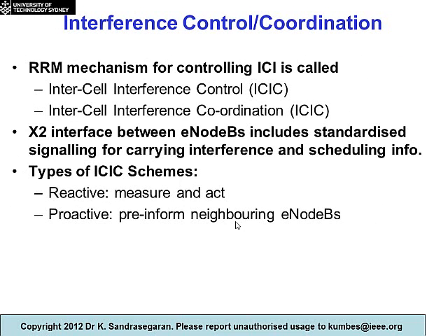Okay, so this is another function that the RRM has to do. Interference control, or interference coordination, is a radio resource management function. Again, it's based on measurements. Remember, the RRM protocols are receiving feedback from the UEs, and they use this to coordinate the interference. The only difference here compared to other RRM techniques is that we need to know information from our neighboring base stations, or eNodeBs.